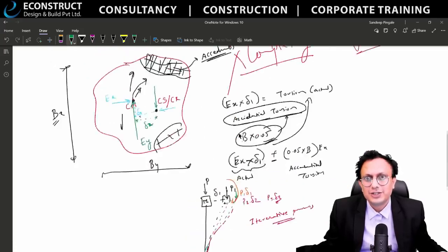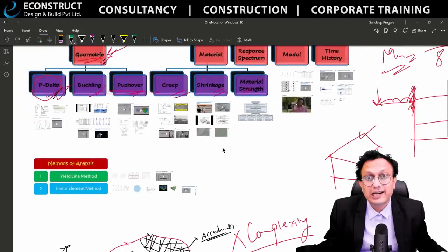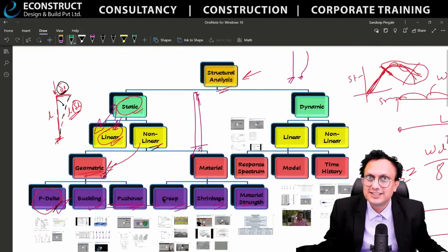All right. So creep analysis, is it really a real type of analysis? Answer is yes. Are we doing it? I haven't heard about it. So is it possible in the Indian code? Yeah, there are 3 lines given in the code with the creep coefficient and all. Is it sufficient? Answer is big no. Then what code will you be using?